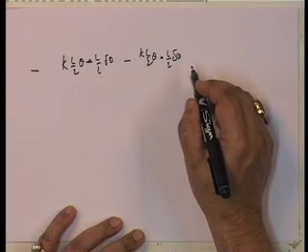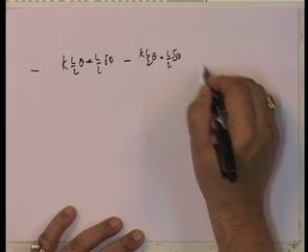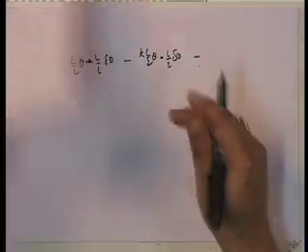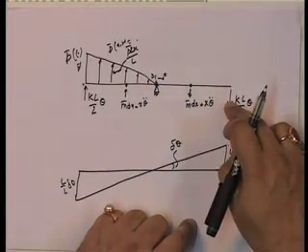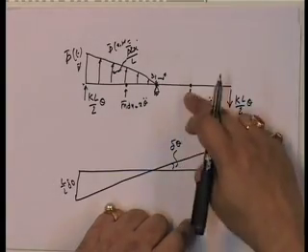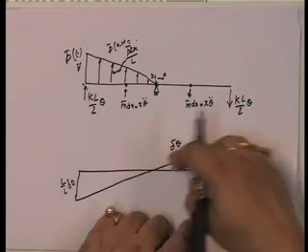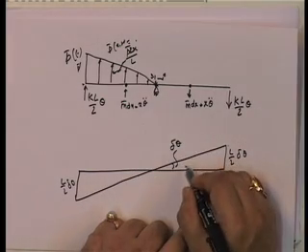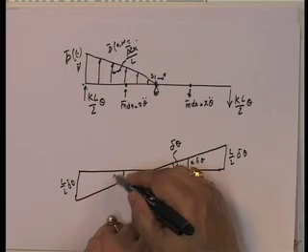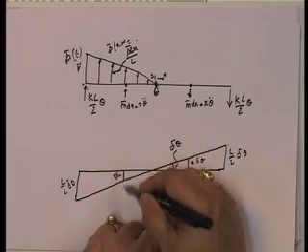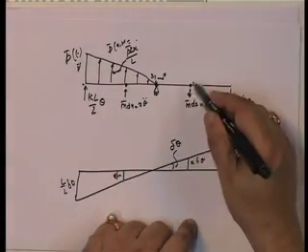And then I have the mass. The infinitesimal mass from 0 to L by 2 has the work done as negative, and on this side also the work done is negative. This is equal to x delta theta and this is x delta theta. This goes one way, and this goes in the opposite direction.